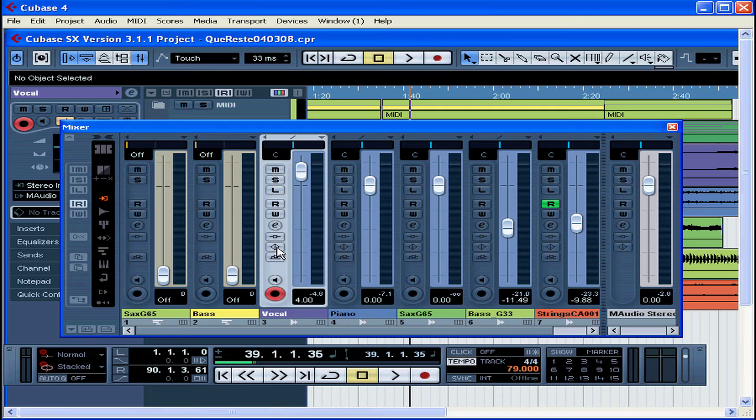Activate this button to bypass any EQ applied to the channel, and this button will bypass any effects that you've sent this channel to, i.e., you won't hear the effects on this track when the buttons are yellow. These are the Monitor On and Record Enable buttons.